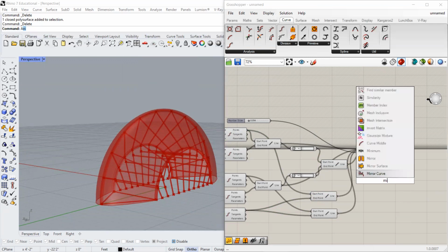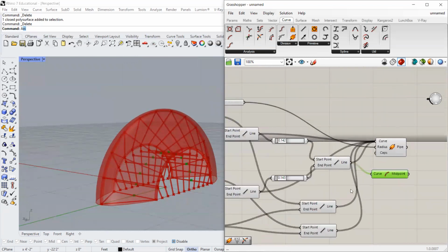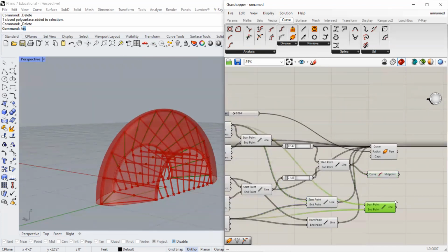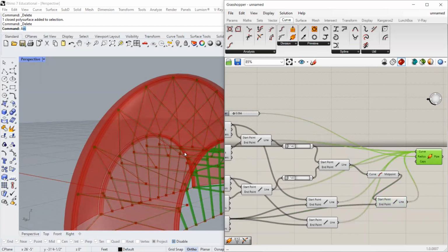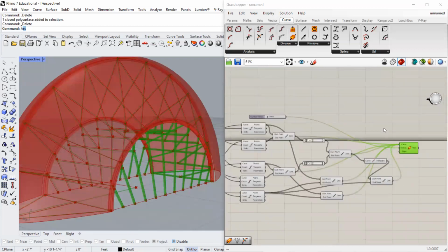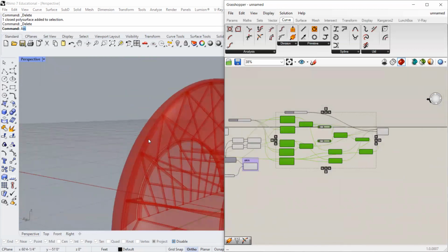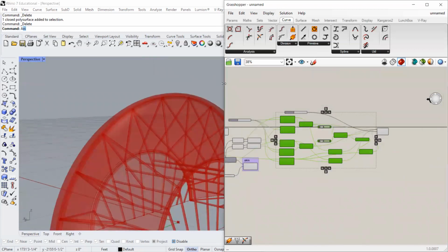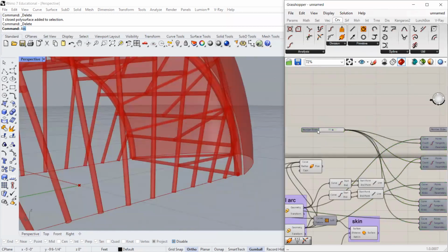There's another version of this. I can just get the middle point of a curve. So if I grab that middle point, push it here, I could create a line from that point to the top and bisect that triangle, pull this out, add this to that mix, and start to get all kinds of fun stuff. So then if I turn off the preview for all of this, you can see that I now have this interesting shell shape that I can pull all these sliders.